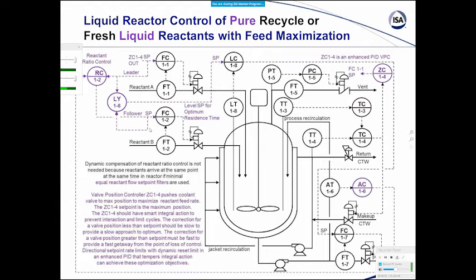And you could choose to somehow do it just on changes in production rate and not in terms of correction for concentration changes. The important thing is always with filters that you be minimal in terms of the time constant. And here with reactants, we want smooth responses. Sometimes with cascade loops, we say, oh, the secondary loop, we just want it to respond as fast as possible. If there's an oscillation, that's okay, because that helps the primary loop get to do its job faster. But in terms of reactants, we don't want any temporary unbalances. We want a smooth response. So we don't want any oscillations.